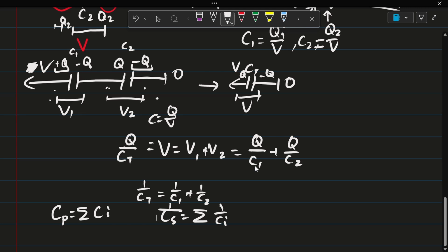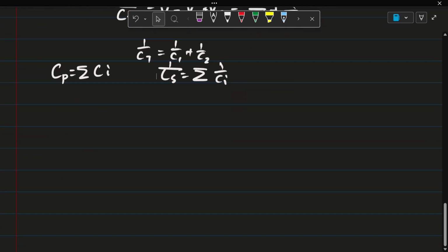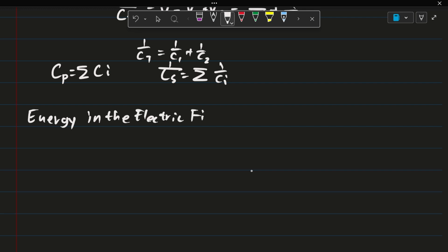Now, we have already discussed a lot about the electrical engineering itself, but we haven't fully asked the question, the energy and where it is stored. In this case, it's the electric field. So let's actually do this kind of idea. Let's first state the energy density called small u_E, which is pretty much the potential energy divided by the volume. And let's do that for the parallel plate capacitor.